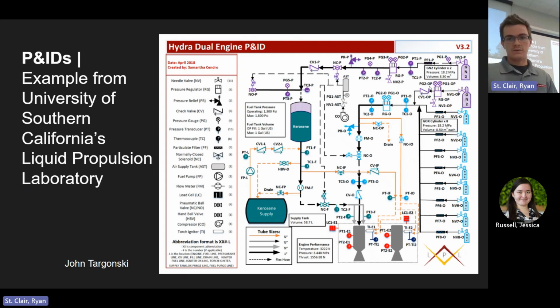So what we have here is a blowdown system again. You can see there's this kerosene tank, and if you look upstream of that, there are these gaseous nitrogen tanks. We can see that it is being read by this pressure gauge. It's going across a particulate filter. There's some electronic instrumentation. Then there's a regulator. These tanks are typically tapped at like 2100, 2400 psi, so you don't always want that full pressure. So you regulate it down to a pressure that you want.